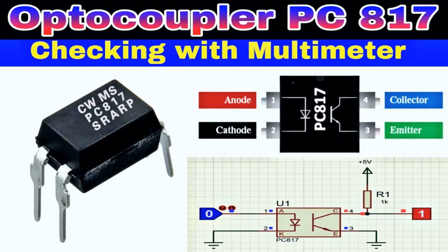Motor control. In motor control circuits, optocouplers can be used to protect the control circuitry from high-voltage spikes and inverter switching noise. Feedback control systems: optocouplers are utilized in feedback control loops to isolate the control and sensing components, ensuring accurate feedback without introducing noise or interference.